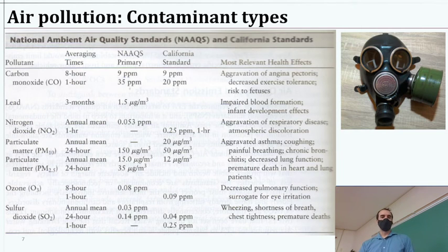Lead, and this is another one. Now you don't get lead in gas phase, but you will get lead particulate matter, so you don't want lead in your exhaust. We used to have leaded gasoline for anti-knocking properties, something about the way engines run. And so we used to be emitting quite a bit, actually, and basically any level of lead is essentially unsafe. So we don't really want any lead. There is a standard, but it's probably more so to do with our detection limit.